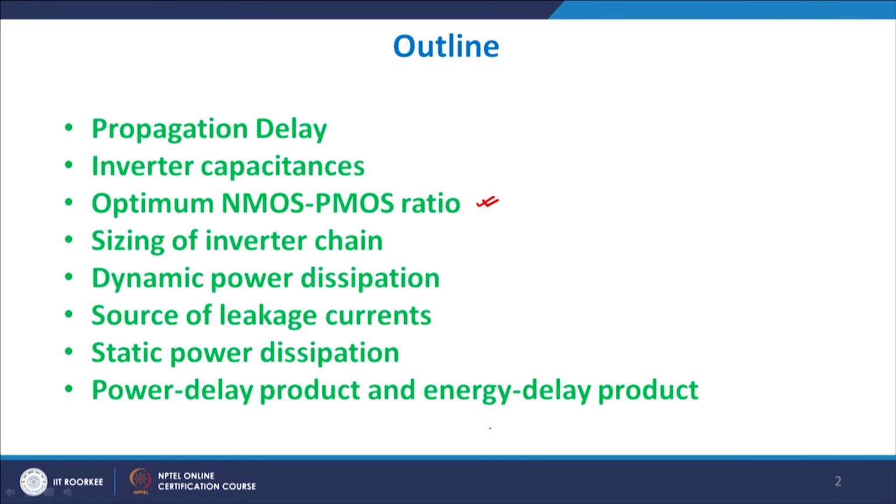If you remember correctly, in the previous lecture, you require that the aspect ratio of PMOS should be about 2 to 3 times larger as compared to that of the NMOS, in order to have a symmetric VTC, or voltage transfer characteristics, with Vm approximately equal to VDD by 2, which is a natural coincidence or a very ideal value.